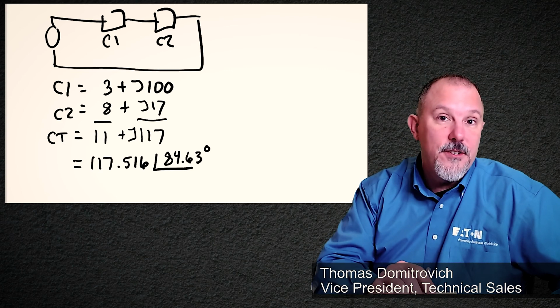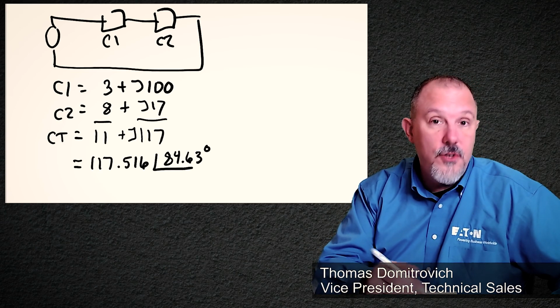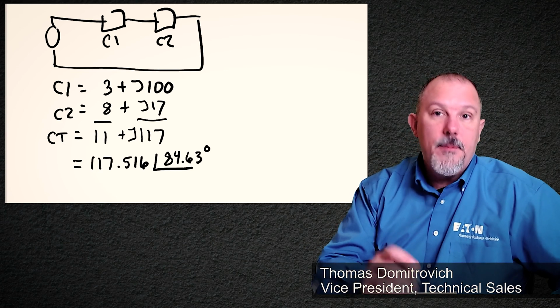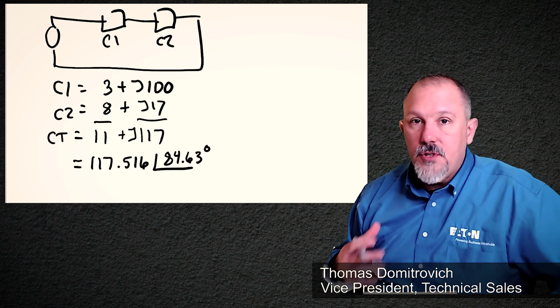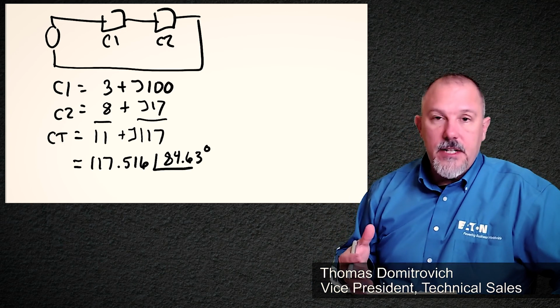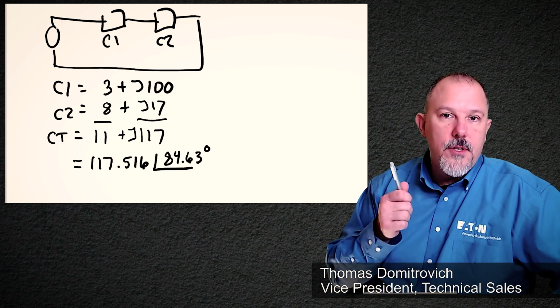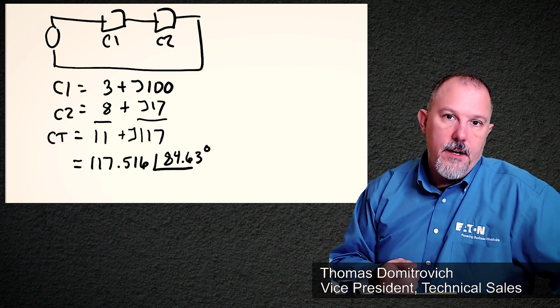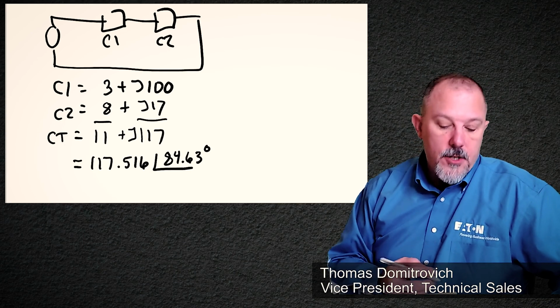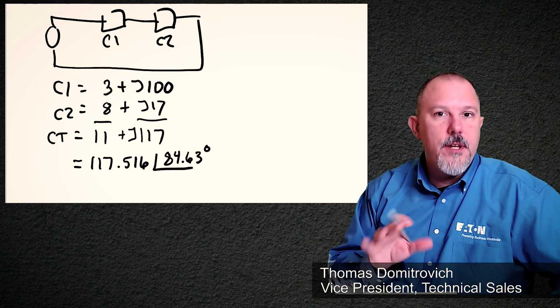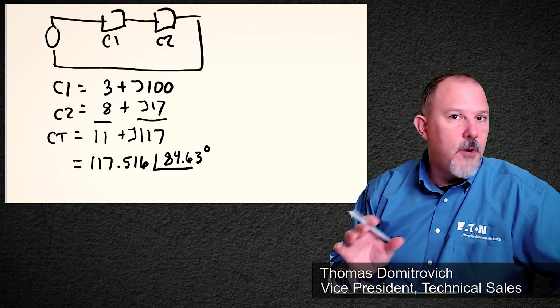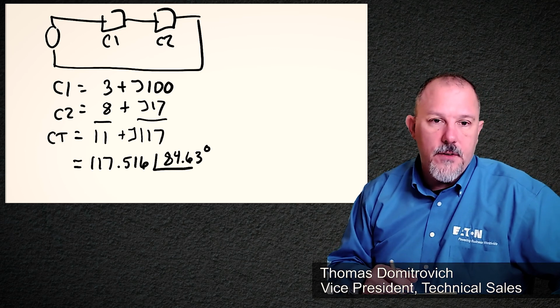Now you might say, boy, that's not very much. And for these two, it's not very much. But if you're looking at a very large power distribution system and you're adding a lot of conductors in series and paralleling conductors, those numbers make a difference. They add up quickly. Especially if I'm using per unit, and then I'm using very small numbers, small changes in decimals make a big difference.